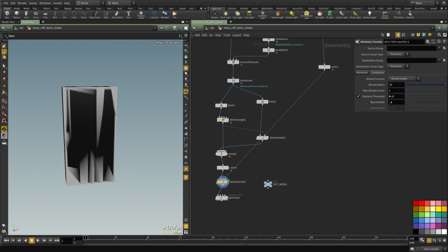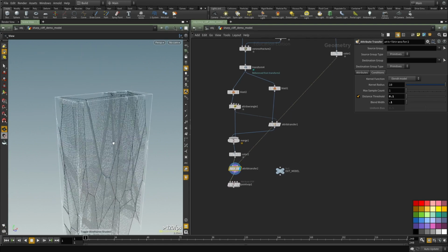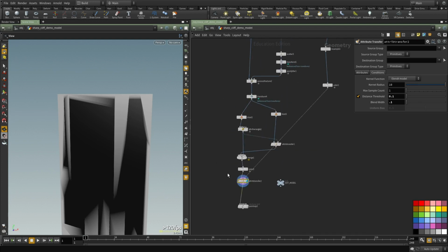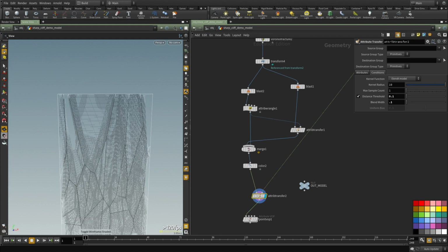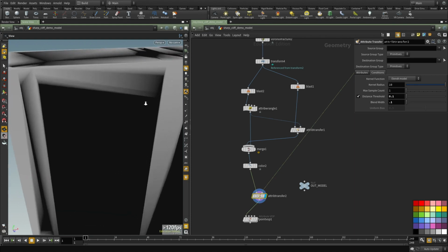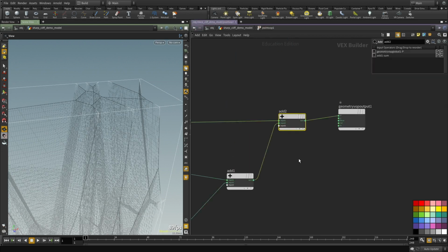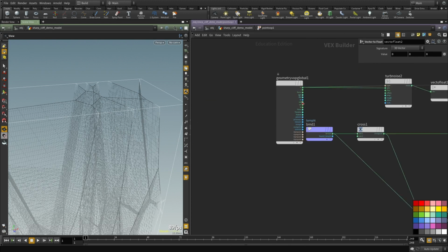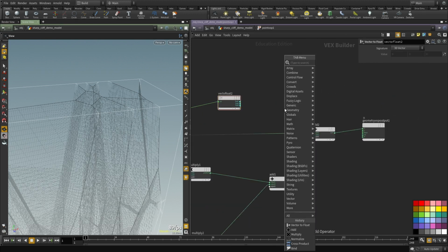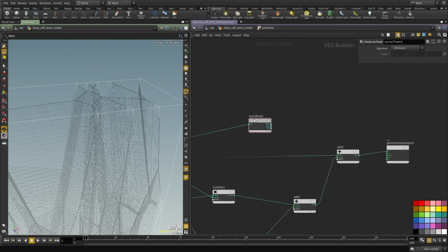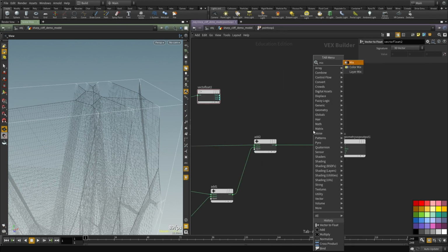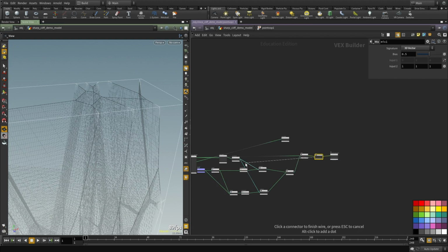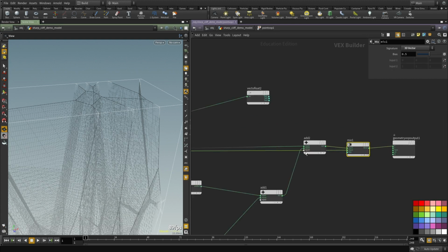We verify something. Okay, cool. So that's what we're going to use as a multiplier for the noise. And let's see. I can add a divide node to help this, but I'm not going to worry too much about that. So now I'm going to import that color here, in the color channel, and invert it, or actually let's keep it that way. So I'm going to mix between the new P, the new deformed position, and the original position, using this mask.